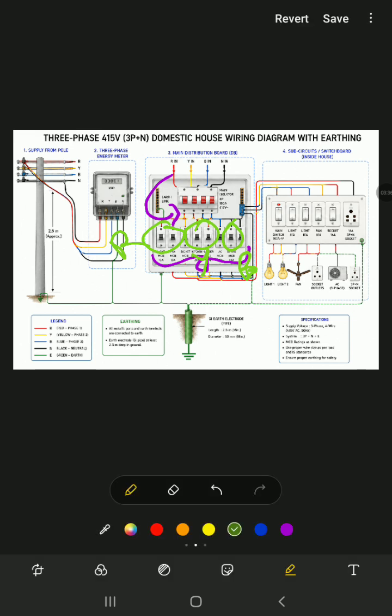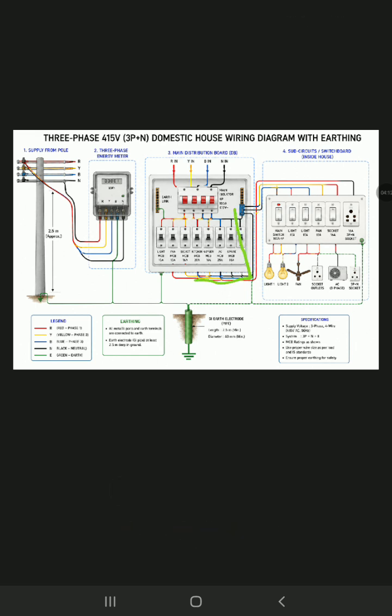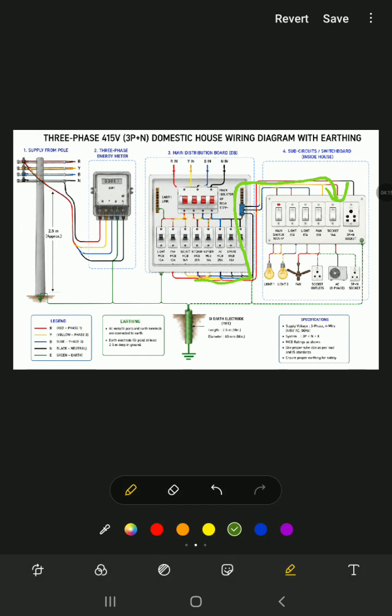The remaining 2 are either for an inverter or separately for neutral, but we generally don't consider a separate single pole MCB for the neutral wire because it may be dangerous and the return phase may come on the sockets. So this phase is divided. Also in apartments and buildings, if there are 3 flats on a floor, R phase goes to one flat, Y phase to the other, B to the third flat, right? House wiring is the same, and the wires go through pipes inside walls to our respective sockets.